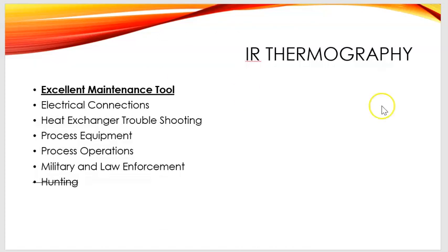In thermography, infrared thermography, it's a good maintenance tool. You can actually see electrical connections. When the electrical connection gets loose, it starts to get some resistance through that connection, which will generate heat. And so you can start seeing the heat that's starting to be generated a little bit more than the other one. We'll see a couple images of that. So it's an excellent maintenance tool to go out and see the connections on your electrical equipment and actually know that they're starting to get loose. They haven't failed yet, but they're getting close to it.